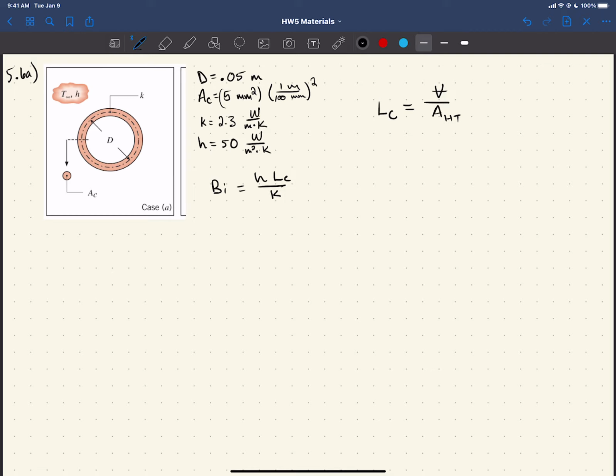But something that kind of helps me, in the back of my mind when I'm trying to figure out a volume, instead of remembering a bunch of formulas, I just think that at the end I need to get a length dimension cubed. And the easiest way to do that is to take some sort of cross-sectional area, if it's constant throughout the shape, and in most of these geometries it is. You calculate that cross-sectional area, and then you just multiply it by either the length, or in this case it's actually going to be a circumference because it's round.